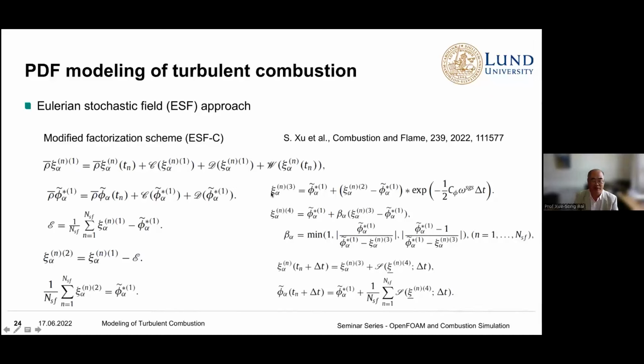If the mass fraction is less than 0, then one can make it equal to 0. Larger than 1, make it equal to 1. Otherwise, in the source term or chemical reaction rate calculation, the code will not be happy to see a mass fraction that is less than 0 or larger than 1. So we apply a uniform limiter instead of an individual point limiter. In this way, we can show that it behaves better, and also it is mass conserving.